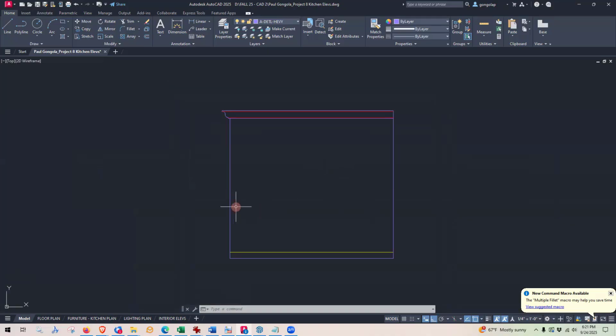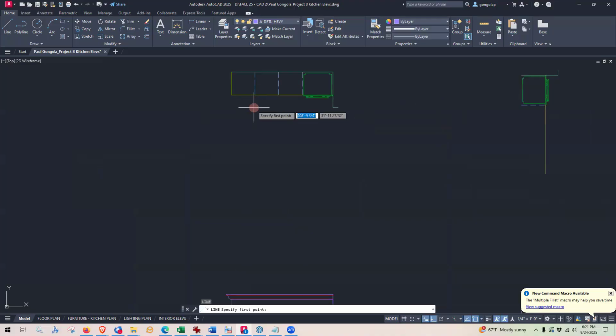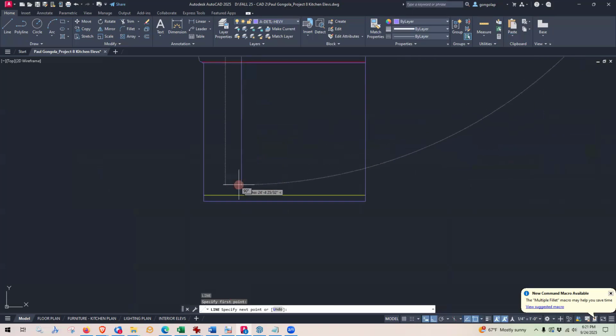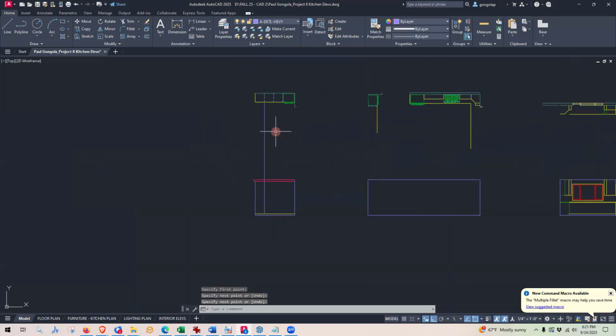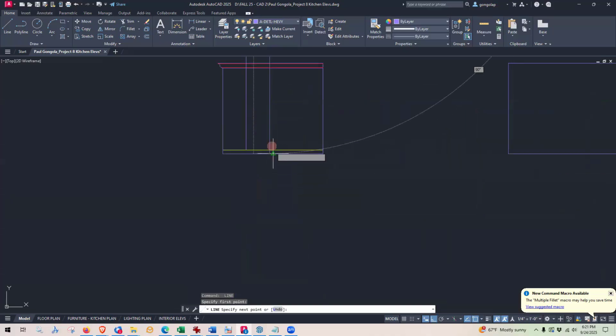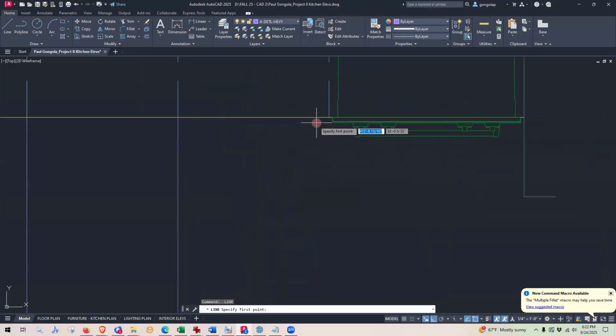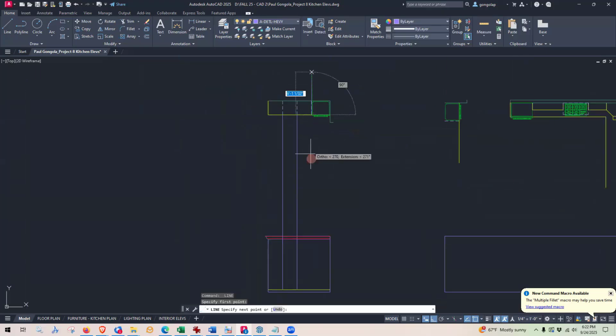So now let's do the millwork over here. I have 3 pieces of millwork, and let me come down, and I'm just going to kind of draw those. At this point, I don't want to be on my heavy line weight. I think I want to be on my light line weight. So I'll change these in a second.